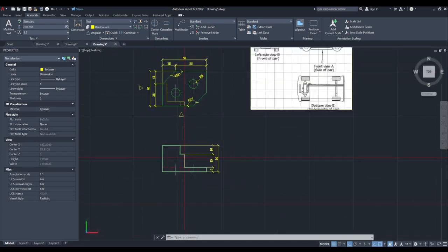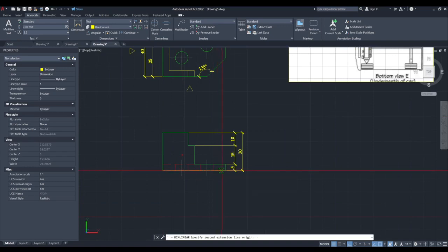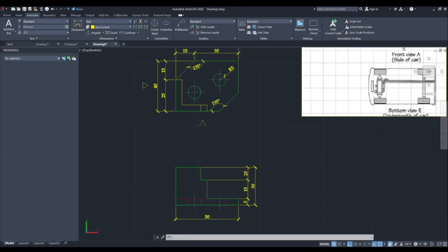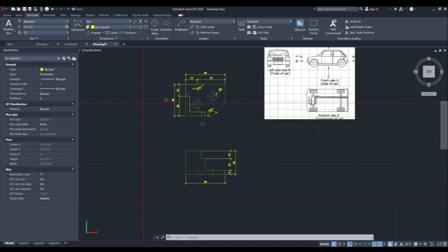Now to make sure that all the dimensions are the same with the top view we created previously, let us create the dimensions again, DLI, showing the bottom of the base plate, and it must have the same dimension, the same length of the top view. Now, in order to create the left side view, it is not easy to create it manually. So there would be some strategies on creating that. So first we have to create the extension line, projecting to angle 45.